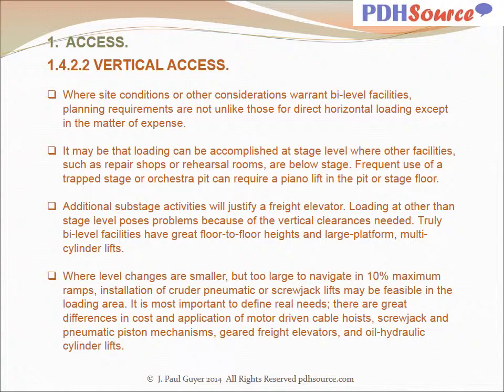Where level changes are smaller but too large to navigate in 10% maximum ramps, installation of cruder pneumatic or screwjack lifts may be feasible in the loading area. It's most important to define real needs. There are great differences in cost and application of motor-driven cable hoists, screwjack and pneumatic piston mechanisms, geared freight elevators, and oil hydraulic cylinder lifts.